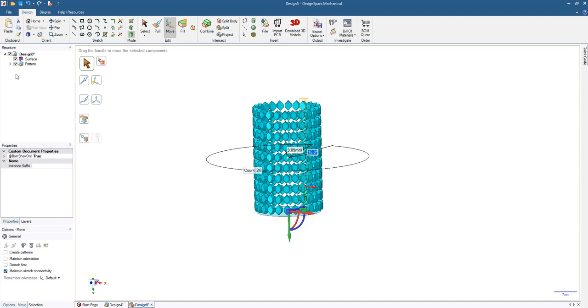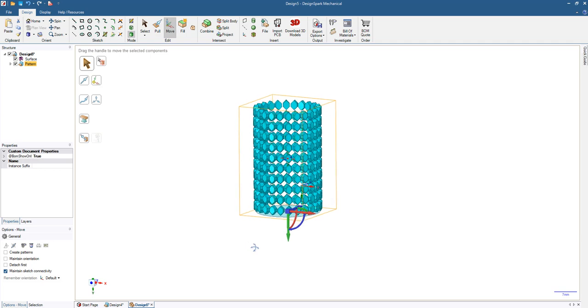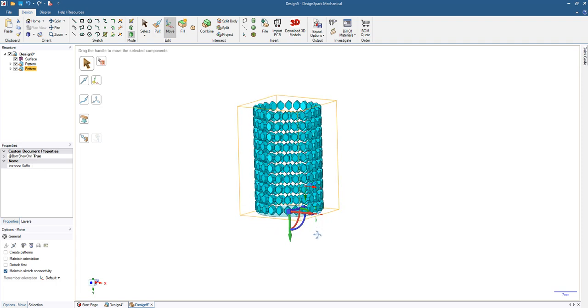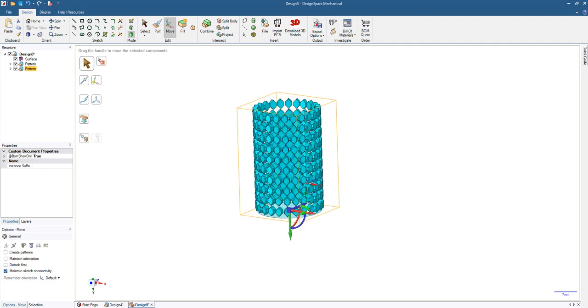So the next thing we want to do is pick that entire group of facets. Hit Control C, which doesn't seem to do anything, but it copied that into memory. Then Control V, which pasted a copy down. Now we're going to rotate the second copy by half of that 15 degrees from earlier, so 7.5.